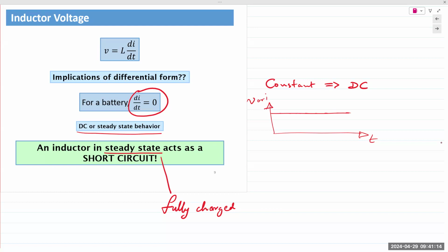That magnetic field gives rise to an opposing voltage. That opposing voltage will resist any change in the value of the incoming current. Notice it will oppose any change in the value of the current. So if the current remains steady, meaning if it's DC, there is no opposition. But if it's AC and the value keeps changing, then the inductor will actually oppose that change.